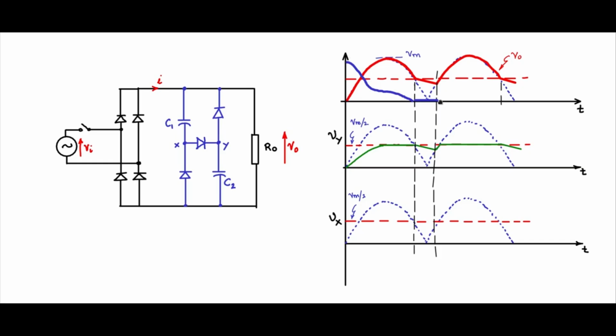The second cycle onwards you will see that it will just be in this fashion. Now you see that the conduction period of this current has been widened so much, and therefore the peak would be significantly lower compared to the normal capacitor rectifier filter capacitor circuit.